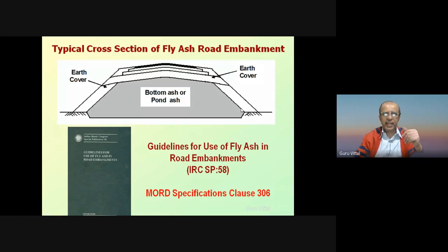So this was the idea. We cannot use a non-cohesive material in an embankment construction open to the atmosphere. If we use it open to the atmosphere, because of rains and even because of wind, it will get eroded. And once it starts eroding, the embankment may fail.